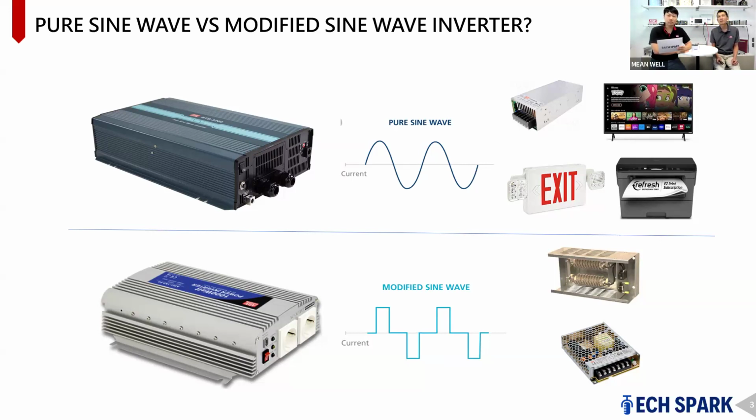If you connect an AC motor, it's not going to turn. Your motor is going to act very weird. Lighting, if you have a dimmer, like a triac dimmer, connected to a modified sine wave, it's not going to work well. I see. But some applications, for example burning a resistor for heating purposes, or powering a power supply, will work, because with modified sine wave the peak voltage is around 150 volts. It can power an AC to DC power supply. So it depends on the design cost. Modified sine wave costs you less.